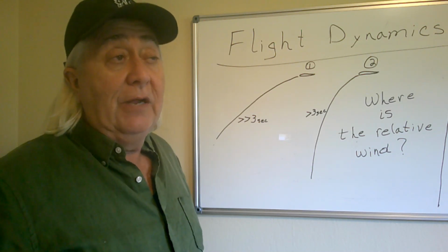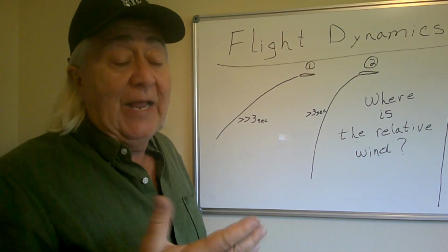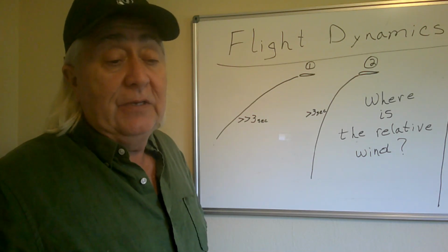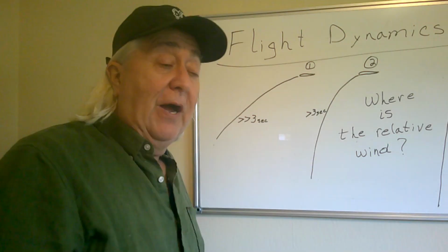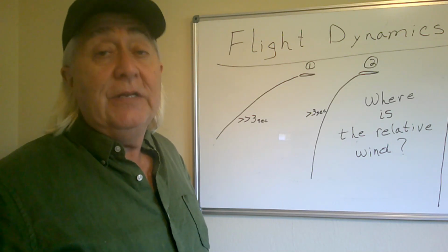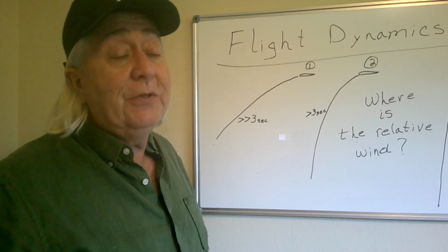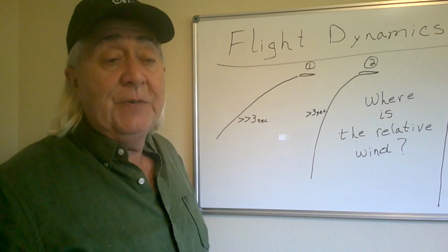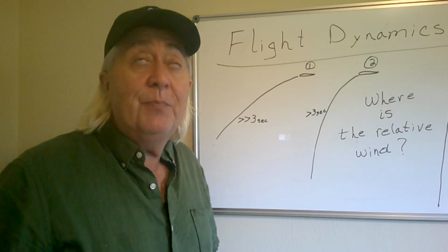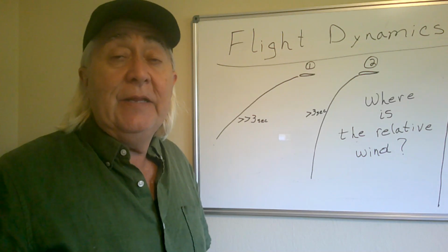I've flown, not me personally, but that pilot had to be thinking, he's not even thinking. He's flying by feel, too high of a descent rate. He's run out of elevator. He's going to pull the flaps up. He just put on a notch. He can't get back to trim speed. He pulls the flaps up. And that could have been part of what he was talking about: I can't get the aircraft trimmed.